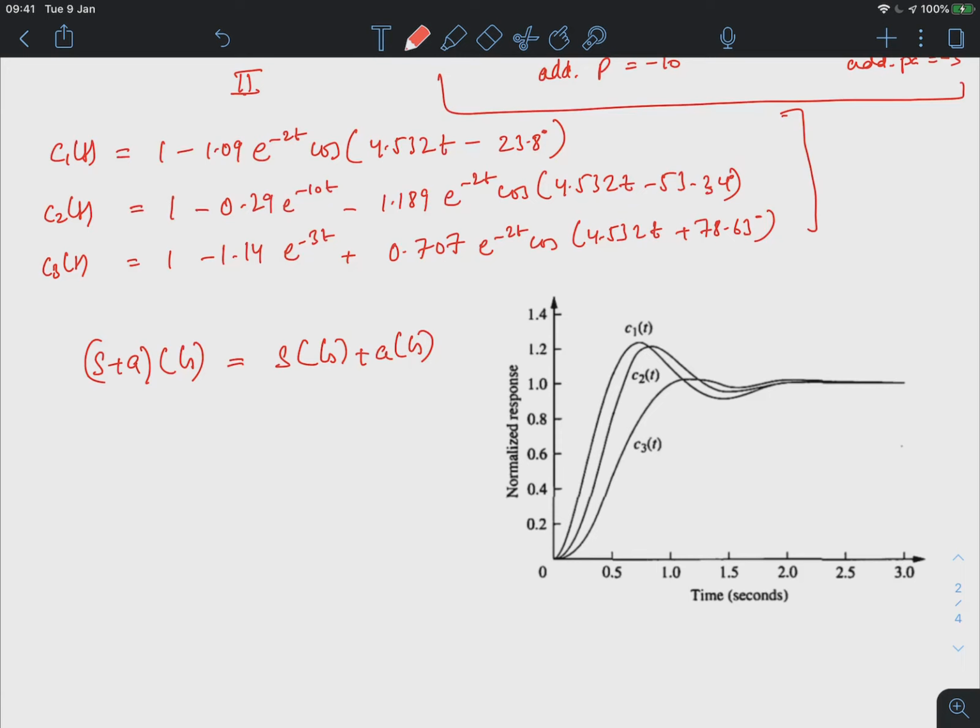Because the system now becomes a non-minimum phase system, meaning to say now we have a 0 located on the right hand side, which implies that the response will initially follow the derivative in the opposite direction from the scaled response. So for the non-minimum phase system, generally we have this kind of response. First, because of this term, it will go in the opposite direction and then it will increase. So the behavior would become completely different, which is much more problematic to analyze.